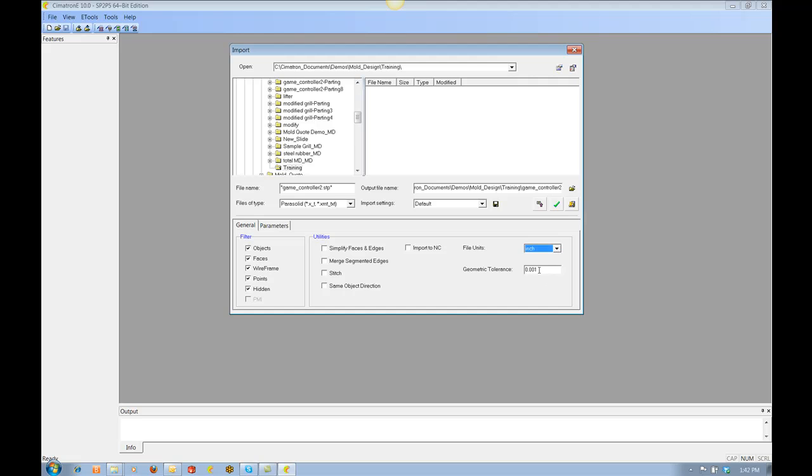And so the parasolid default tolerance is 0.001 millimeters, and the default tolerance for step is 0.01. And I have seen examples where tightening this up a little bit was better, and I probably would just try like 0.005 millimeters if I wanted to see a different result.